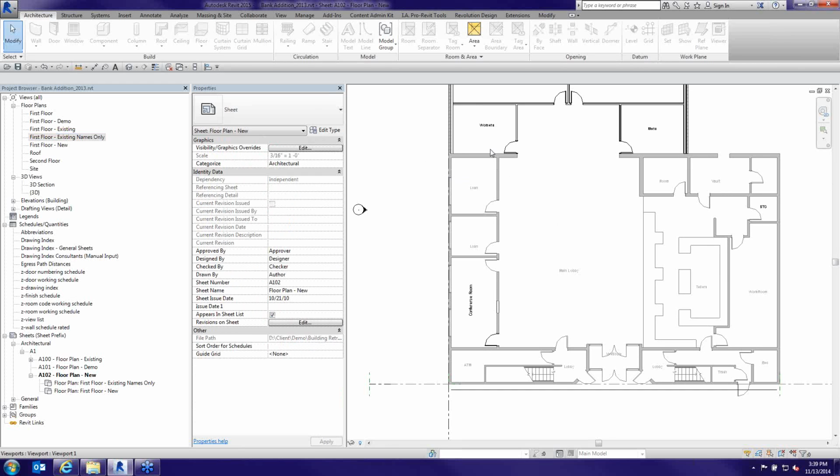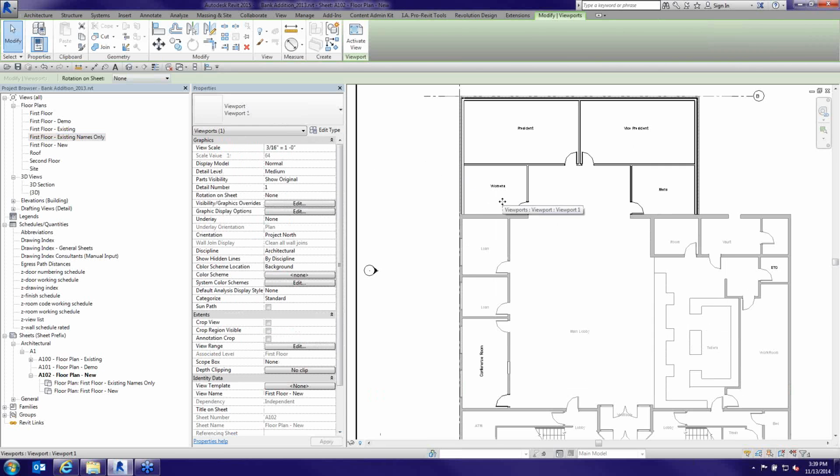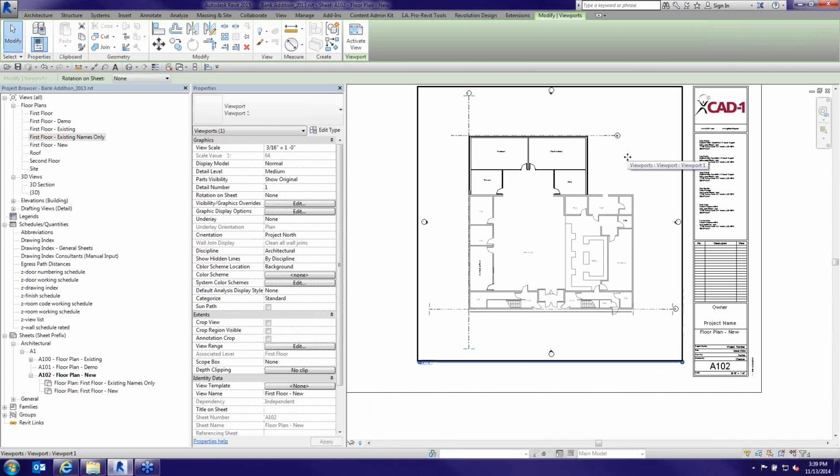So that's a question that usually comes up in those scenarios, how do we go through and set that up, etc. Okay? Now, one of the key things inside of here is when we're dealing with consultants. So for the architects, mostly in the room, and the engineers, you might want to listen to the structural engineers, Revit MEP has a lot of difficulties using phasing. So phasing for Revit MEP, when you start talking systems, you have to cap a system before you can demo a portion out of it.